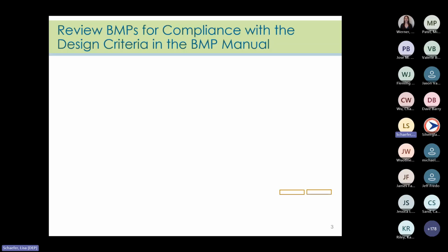All right, so as Rachel indicated before, each subchapter of chapters 9, 10, and 11 has a section titled Design Criteria, and a BMP needs to be designed to comply with all of the specified design criteria. Otherwise, it doesn't merit the approved TSS removal rate required to address water quality. So let's look at the kinds of BMPs included in the stormwater management rules.